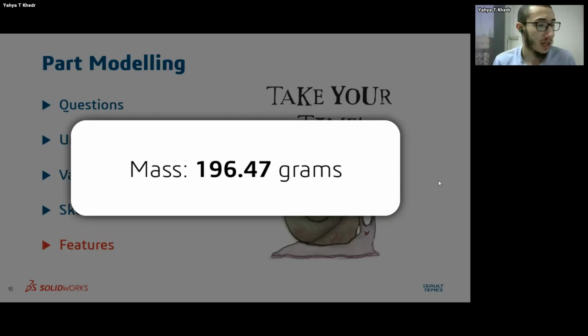And then I also said, okay, why not save myself a couple of features instead of doing the extrusion in one feature and then the cut in a separate feature. I just said, okay, let's do them both in the same feature. So different things went through my mind, and I'm pretty sure that the result is the same regardless of how I did it. It's all about how fast did I do it, and the other thing is how easily can you edit or modify this, which is going to take us to our next point.